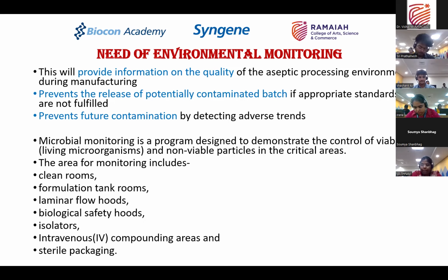Then the isolators. When the product is taken from one place to another place, from one clean room to another clean room, those isolator areas, whatever isolated areas are there, those also have to be covered or monitored. Then intravenous compounding areas, when the packaging system is happening, when the product is getting packaged into sterile containers. So during packaging, during intravenous compounding, all these areas have to be monitored for viable and non-viable particles.